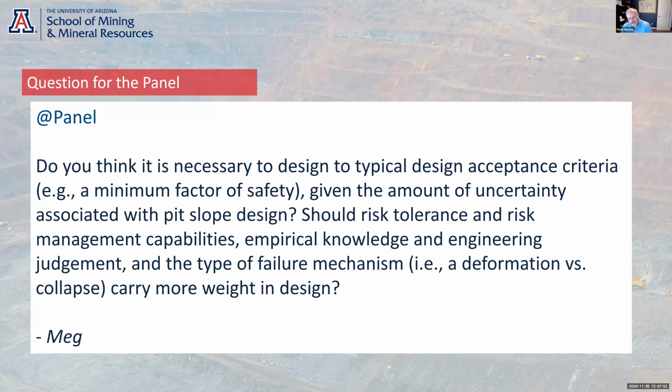Getting the mechanism right is so important, and I would argue that we don't get it right very often, particularly on a greenfields kind of assessment. And our fallback is always, okay, we've got a design going forward that's based on some kind of acceptance criteria, and now we're implementing that design, and inevitably we move towards an observational approach where we instrument, we monitor the deformation, we adjust the design, but we're probably never actually creating that same design and maintaining that same factor of safety that we had at the initial design.